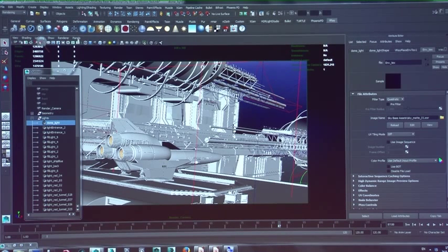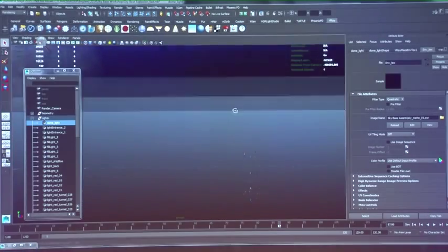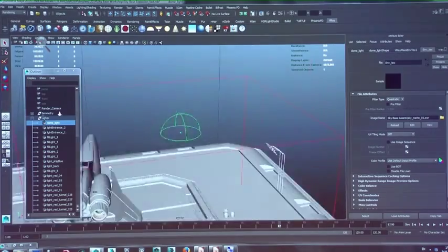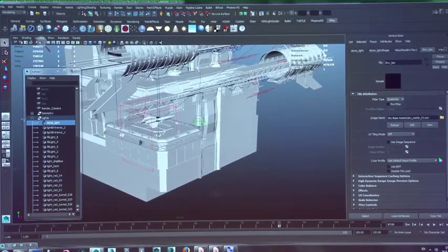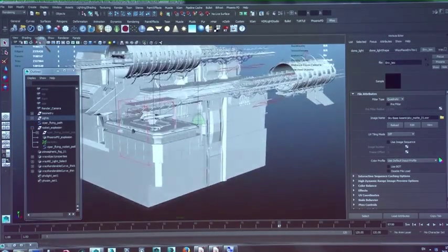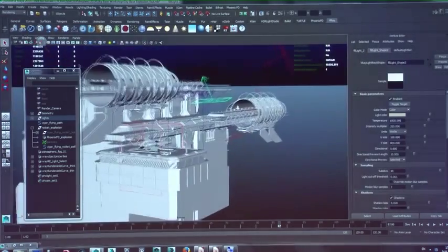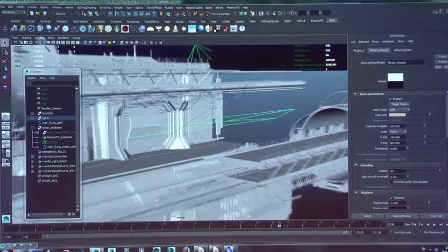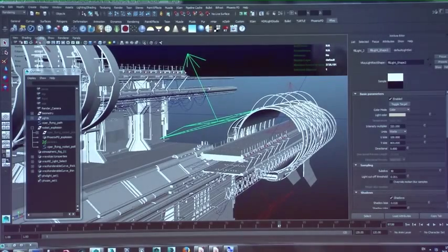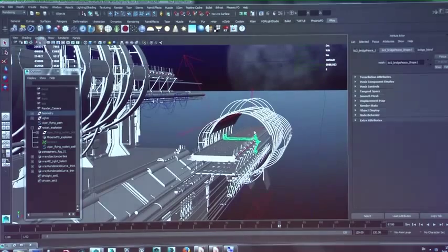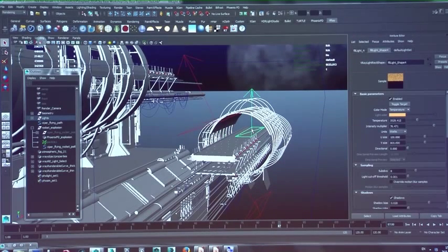However, again, I needed to have a little bit of control. So what I did was actually created a couple of lights here and there to fill in just a couple of volumes. For example, I needed some more illumination below that bridge over here, a little bit of light inside of that tunnel. So I just created the simplest source in V-Ray, the V-Ray rectangular lights, which does a great job for almost every situation.